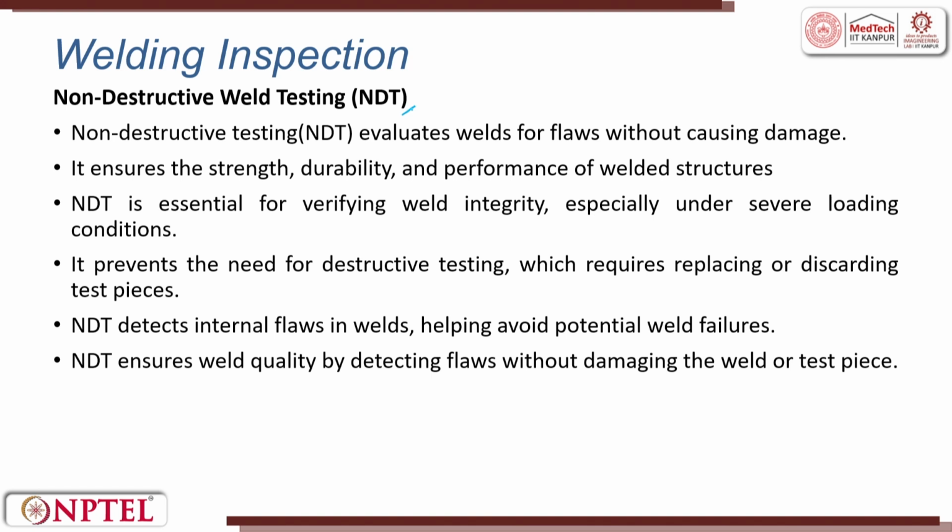Now, there are also non-destructive testing methods which can be used in the forging process as well as in the casting process. Several non-destructive testing techniques are available today to find out the defects and flaws. Why are we doing non-destructive testing? Because we want to evaluate the strength, the durability and the performance of the weld by looking into the response from the non-destructive testing. NDT is essentially used to check weld integrity, especially under severe load conditions. Otherwise, replacement or discarding of these pieces will happen. Finding the internal flaw in the weld helps to avoid failure.